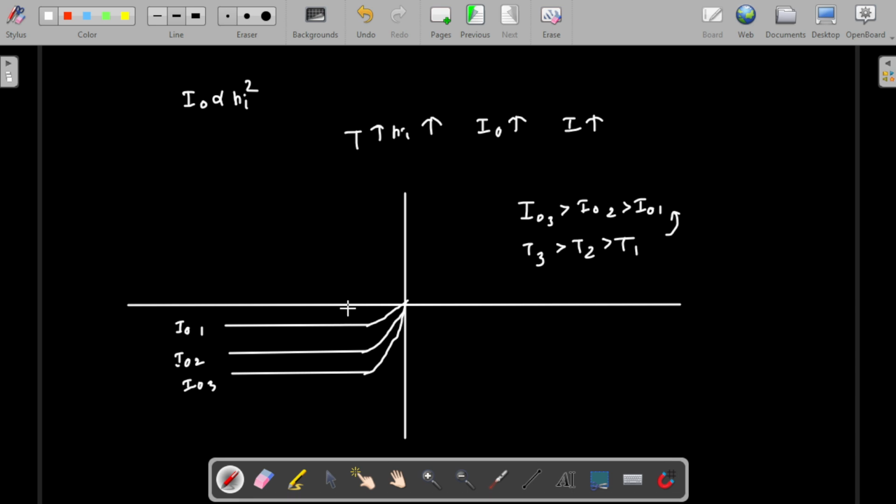These reverse bias and forward bias characteristics contribute very much to everything. So we need to analyze the material in both reverse as well as forward bias. From an examination perspective, we may need to handle anything, in the forward direction as well as in the reverse direction. So now if the diode is operating in forward bias, then we will be getting more current, which is exponentially increasing. But if the diode is acting in reverse bias, then we will be getting only some reverse saturation current.